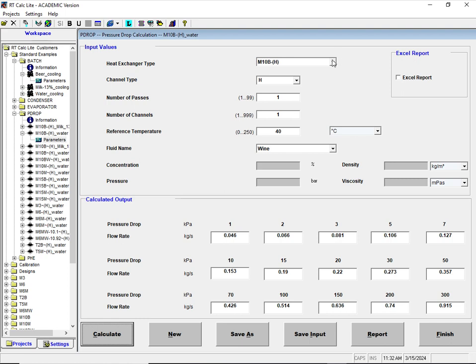And then, of course, as you change the plates, just talking through what we mean when we talk about H, M, and L. An H plate, they typically call it a hard plate, has a very large included angle between the two parts of the chevron. A very large angle. These generate very good heat transfer, a lot of turbulent moving things around, but they have a high pressure drop associated with that.